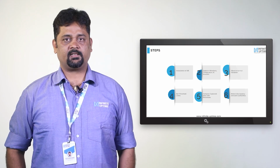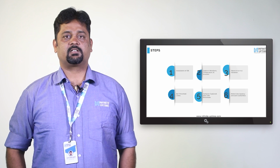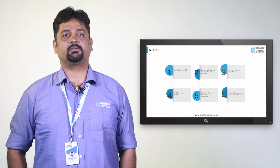To be more precise, it has 6 basic steps. Installation of IDE on the selected assets. Configure and capture vibrations, temperature and acoustic. Observe normal vibration. Set threshold limits. Compare captured data with thresholds. And detect any discrepancy to alert authorities through SMS and email.